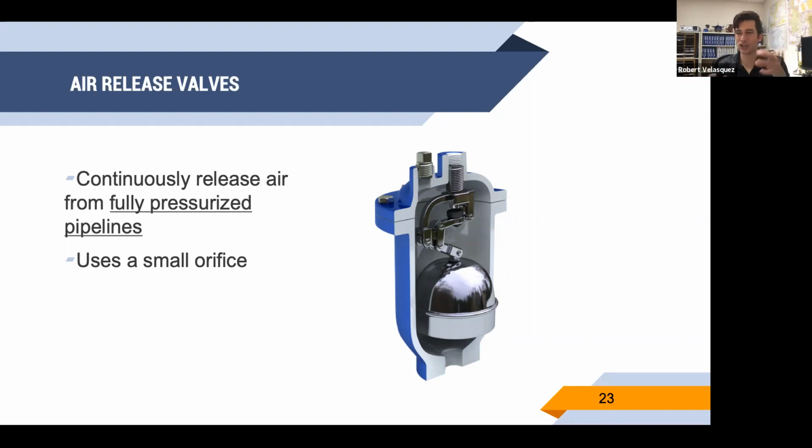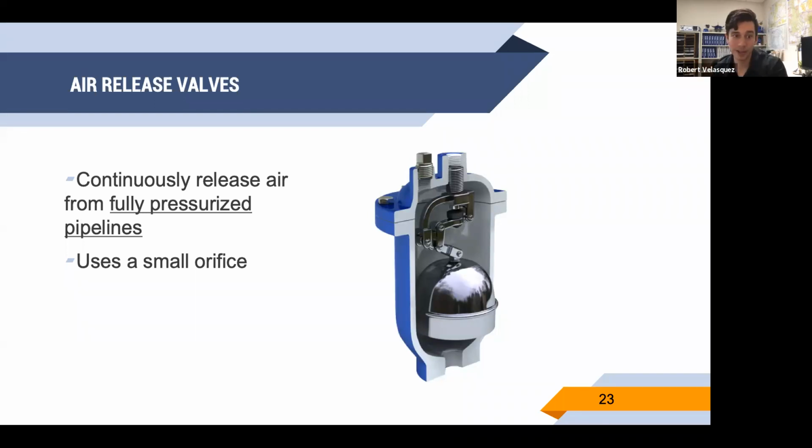And so you get that entrapped air in your water system and it collects into these high spots. It goes up into this valve, and then this valve will just gently bleed it off, and it'll open when it needs to, and then it'll close when it needs to.